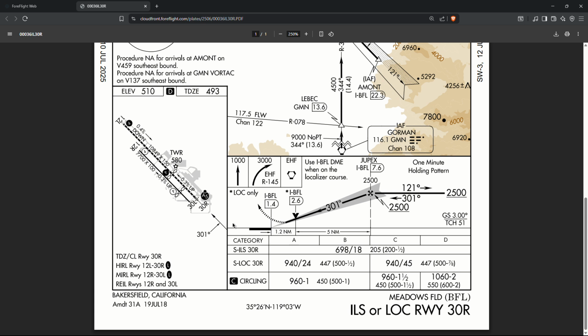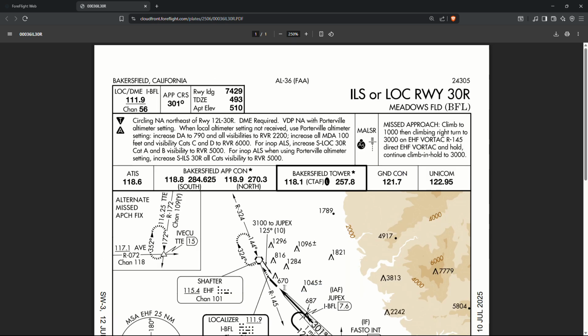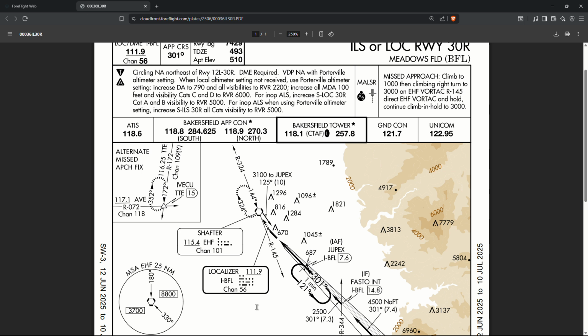So we know for the ILS, we're going to have a DA of 698. And as we're coming down, we're holding that to our minimum. Once we hit that, we go missed. More information about the distances, and then if we shoot the localizer and the circling approach. So precision approaches, really strong. Can be complicated depending on which ones you shoot. The one we shoot here in Bakersfield, fairly simple, nice, easy training one.